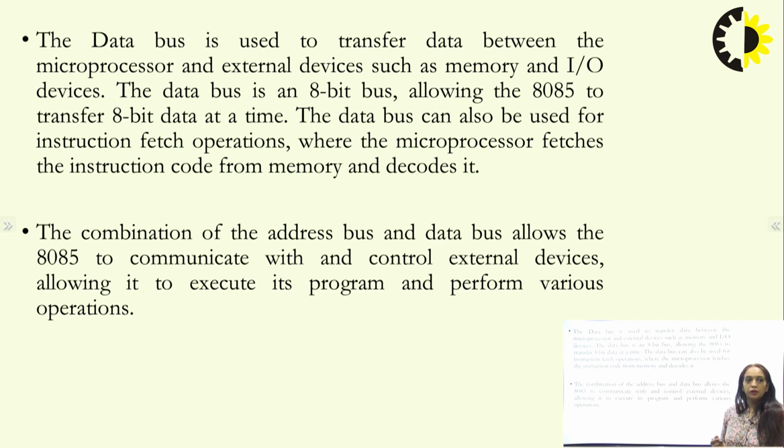The combination of address bus and data bus: the 8 data lines are multiplexed with the address lines also, and that can be extracted with the help of the ALE signal.